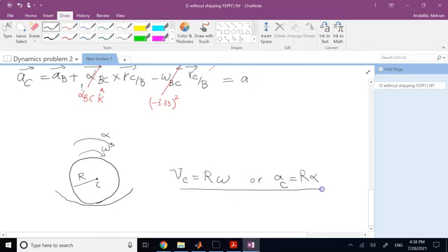So these are conditions for rolling without slipping in general, right? So here I can find A of C directly from disk and say, since this is going with alpha of the disk, and here I assume the alpha of the disk is either positive or negative, okay? So here, let's assume that alpha of the disk is negative.